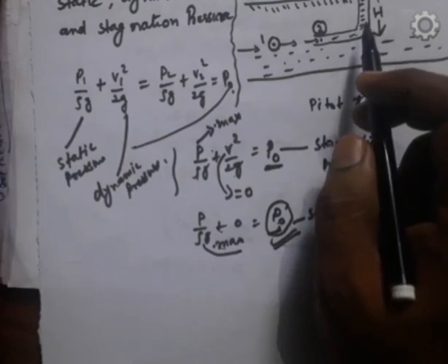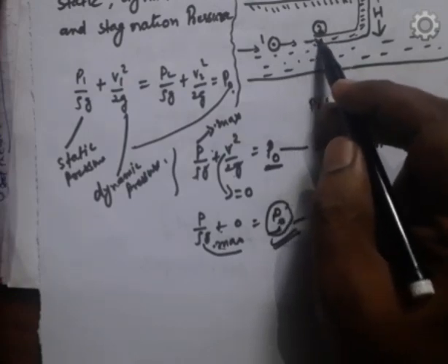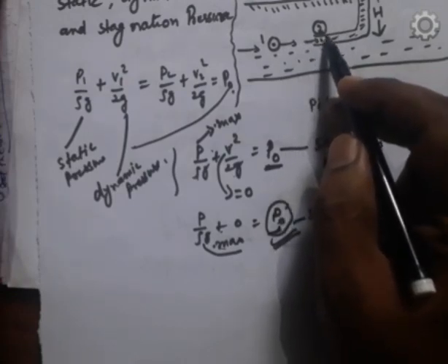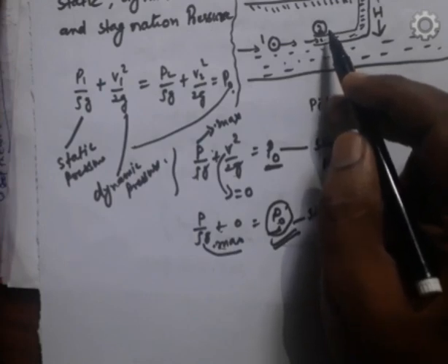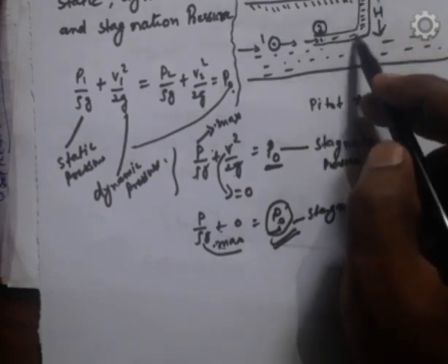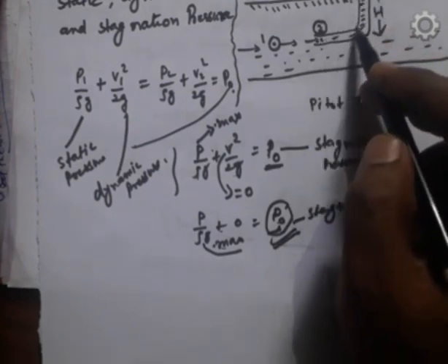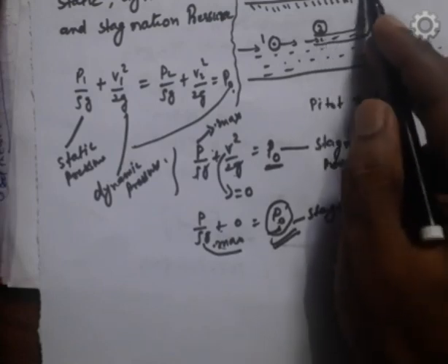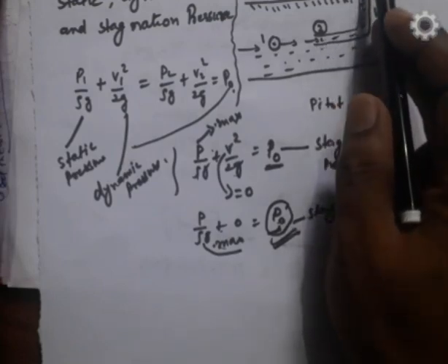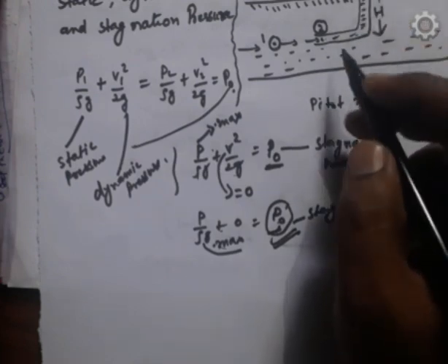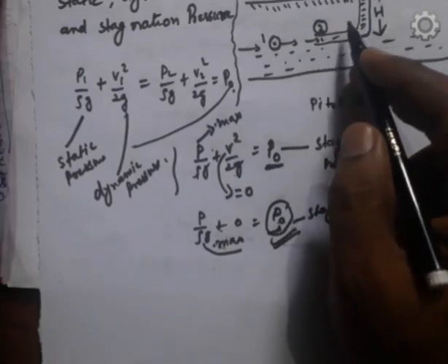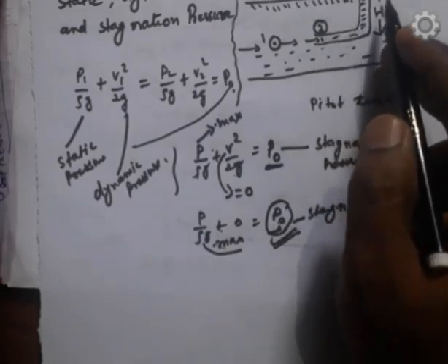It is based on the principle that the velocity of a flow at any point becomes 0. Then the pressure is increased due to the conversion of kinetic energy into pressure energy. In its simplest form, a Pitot tube consists of a glass tube bent at a 90-degree angle. The liquid rises when the velocity is 0, due to the conversion of kinetic energy into pressure energy. The velocity is determined by measuring the rise of the liquid in the tube.